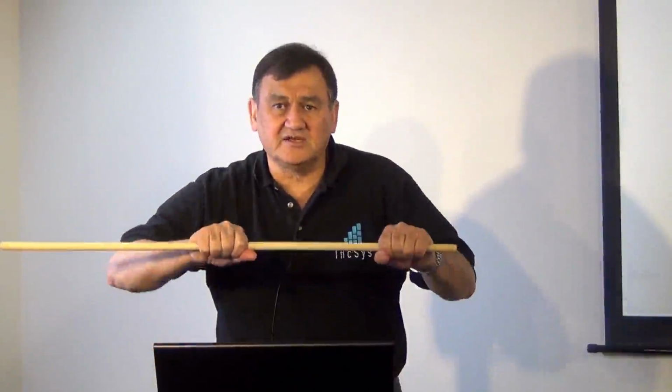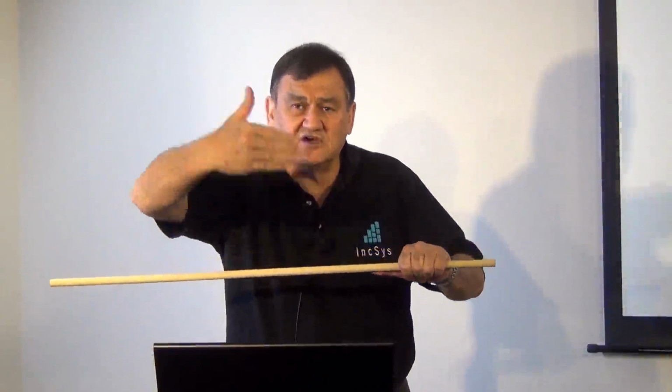They have a huge net reactive load on the system. That can be aggravated as you have a line tripping out of service, overloading other lines. That increases the reactive power loading on the other lines. You can have reactive equipment outages. You can have generators going offline, capacitors being faulted going offline.